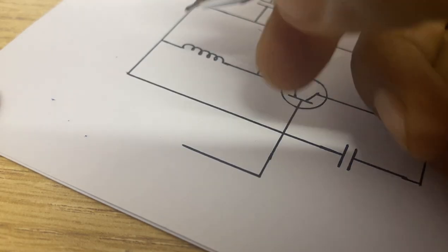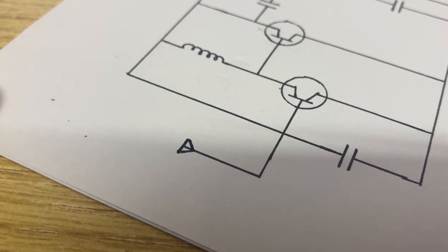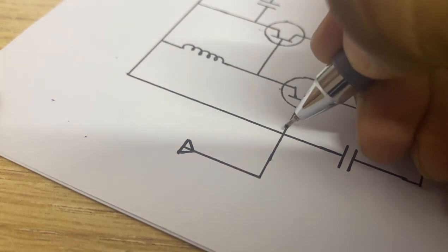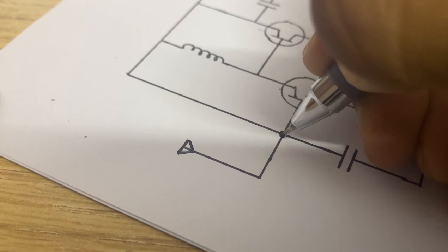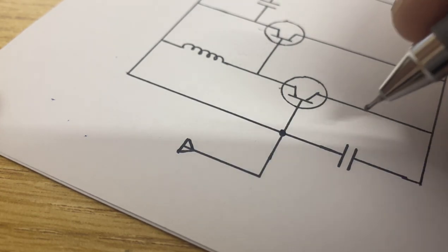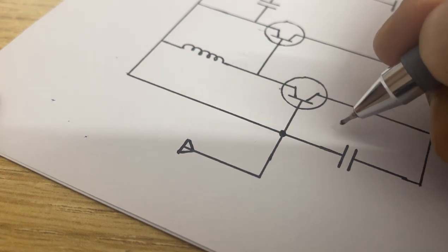So the first part in any communication system is antenna. We will be using a monopole antenna in this circuit or any wired antenna. Later on, for detection of the frequency in the circuit, we will be using a Colpitts oscillator which comprises of an air core inductor along with capacitance.